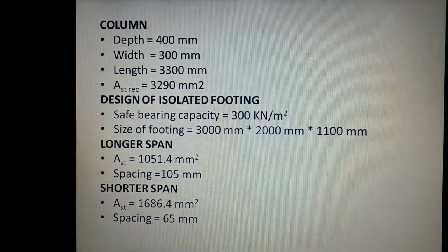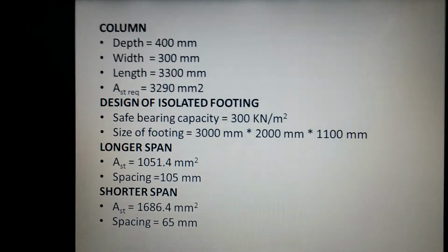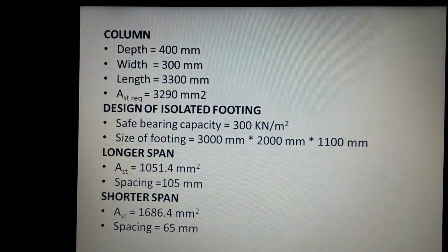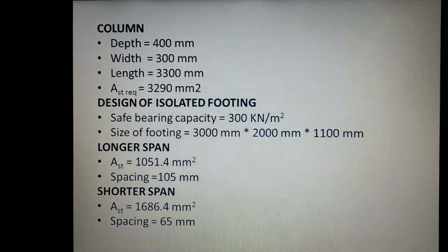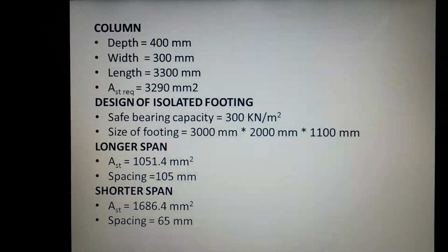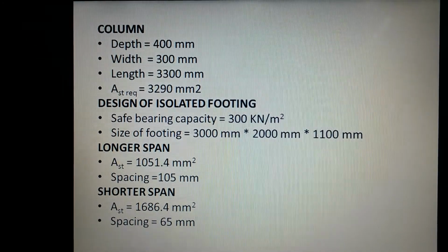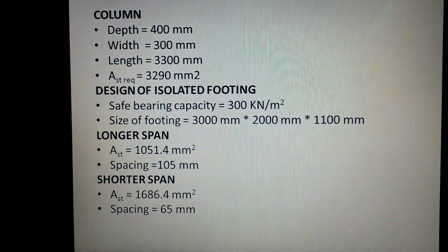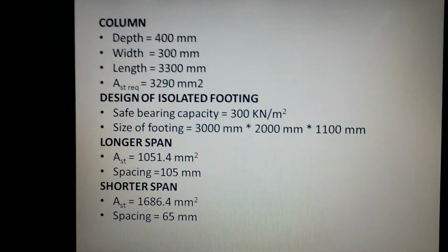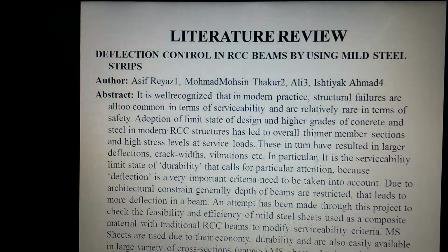And for the footing design, the safe bearing capacity is 300, and the size of the footing we provided for the maximum reaction force is 3 meter by 2 meter, and the depth is 1.1 meter. And the corresponding Ast and spacing is given.